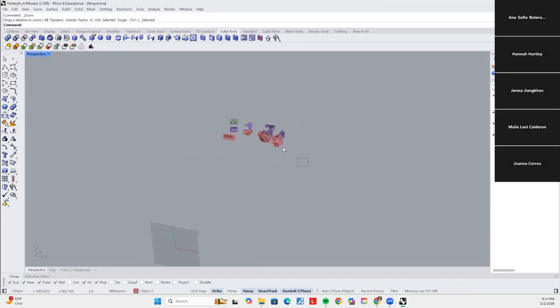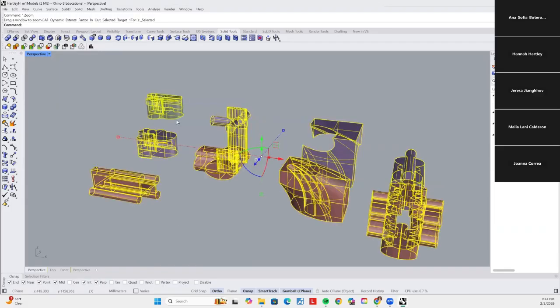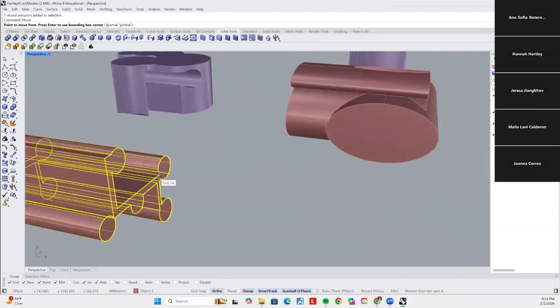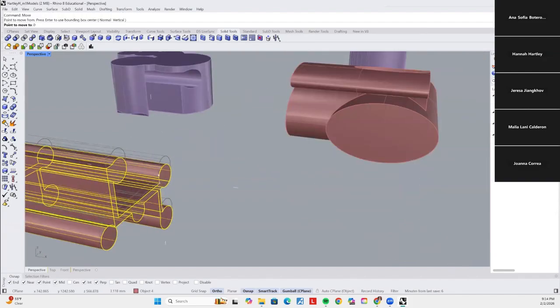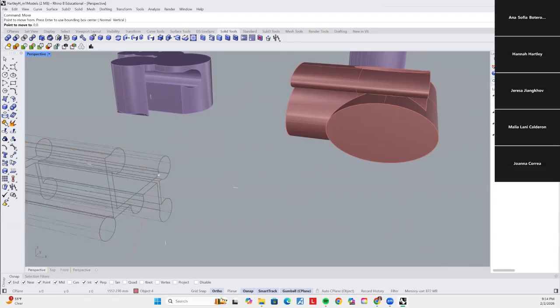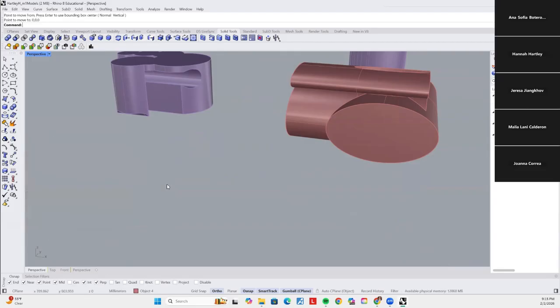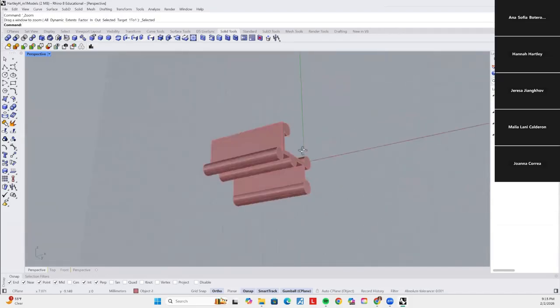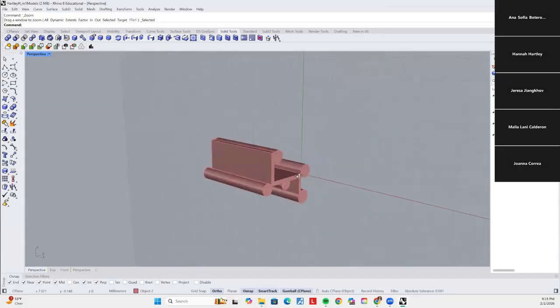So all I'm gonna do is press zoom select, grab each item and press move, click a certain point and do 0, 0, 0. Then it should be selected, so I'll do zoom select and I'll see that it is at the C plane.